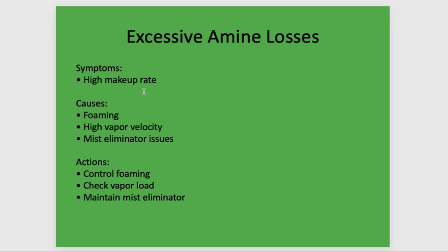This is high makeup. How do you notice excessive amine losses? Daily you should take the concentration of the amine. If you are working with DEA, diethanolamine, you are working with a concentration of 25%. So if this concentration decreased and you start to add some water, this means that you lose amine from your unit by evaporation, or by losses to flare or from a PSV.